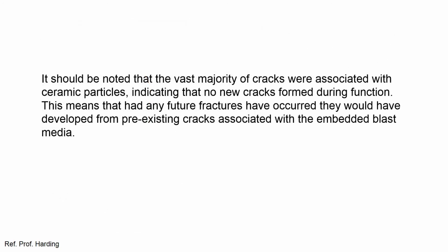So bearing in mind that these were functioning implants removed for biological reasons, not because they were fractured, it should be noted that because the vast majority of the cracks were associated with ceramic particles, this indicates that no new cracks were actually formed during function. This means that had any fracture occurred in the future, they would have developed from pre-existing cracks associated with the embedded media.